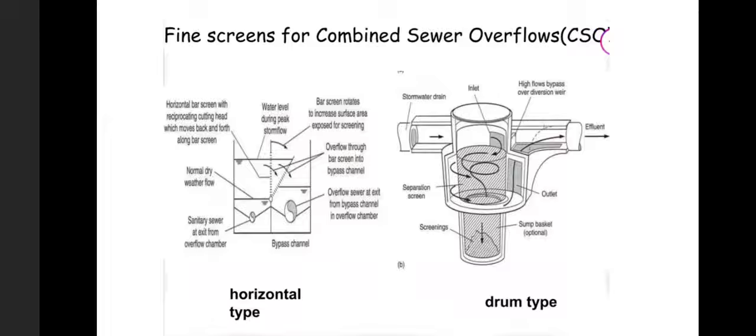Here, the water will enter the screens from the top, and it will be directed with the help of different screens placed in a horizontal way, and the water will flow in a zigzag manner. In each zigzag we have placed a fine screen mesh, so the fine particles below 6.5 mm are collected in the mesh.